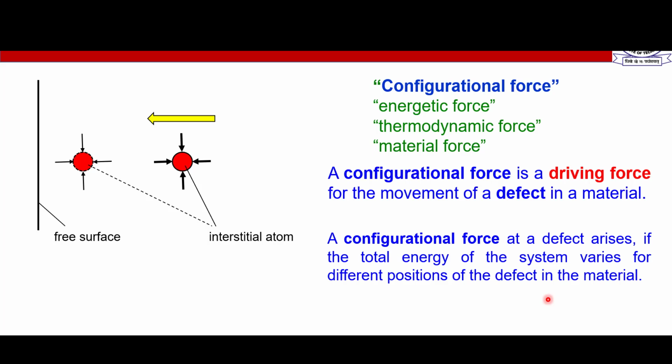So this concept of configurational forces has an advantage that it does not assume anything about the material's constitutive relation. So it can be elastic, it can be plastic, it can be a creeping material, it can be viscoelastic, any type of material, you can use this idea. And the idea is very simple, that when you have an energy gradient, you have a force.